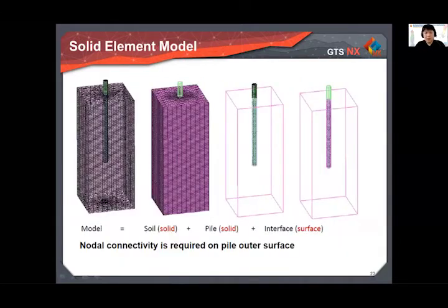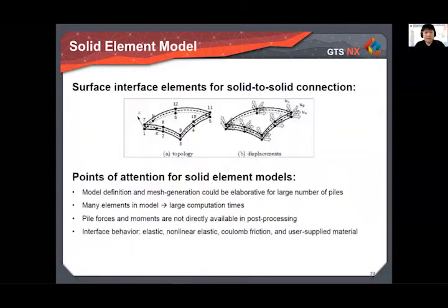This slide shows the typical solid element for the pile. You can see the solid for soil and the pile, and you can also consider the interface between the pile and the solid. But please keep in mind that nodal connectivity is required on the pile surface.